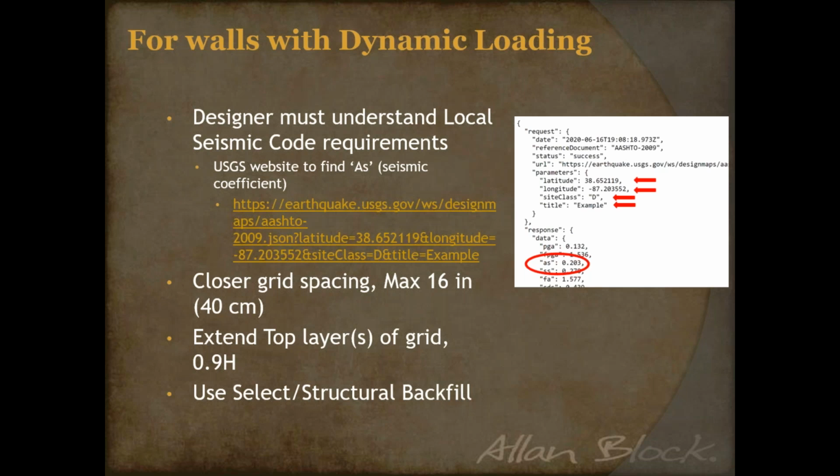Even though we didn't get a direct correlation in our testing, we know through personal experience that building a better wall or better backfill is going to give you better results, especially then you don't have to worry about potential liquefaction of clay soils. If it gets a little wet and then a dynamic load, it could actually liquefy, and now you've got no strength in that soil, and it could actually bulge and fail that retaining wall.